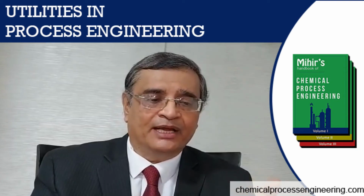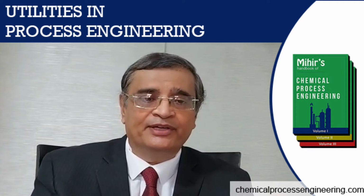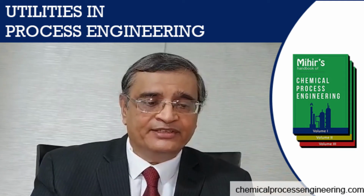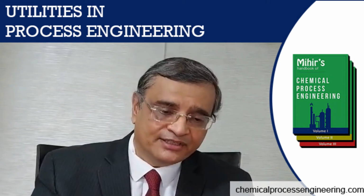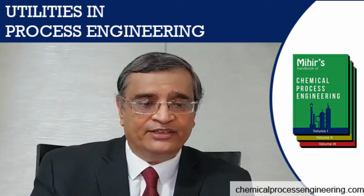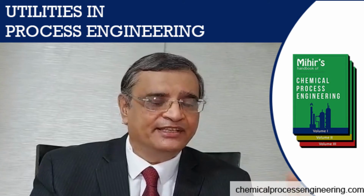Now when we talk about compressed air systems, once the process flow diagram is defined, the next step is the P&ID, the piping and instrumentation diagram. There you define the exact requirements of the on-off valves as well as the control valves. From this, the usage of instrument air and plant air is estimated, and based on that the design of the compressor system is formed, specifying the capacities and the equipment required.